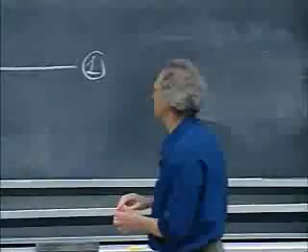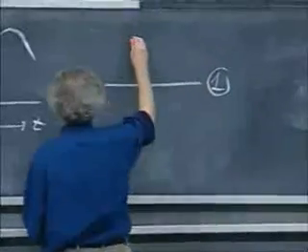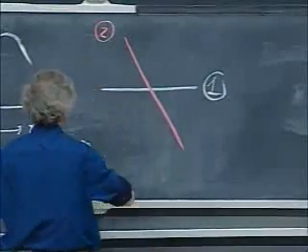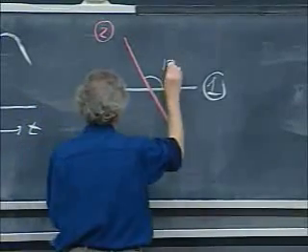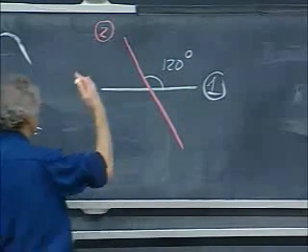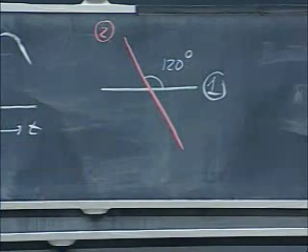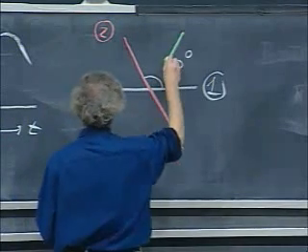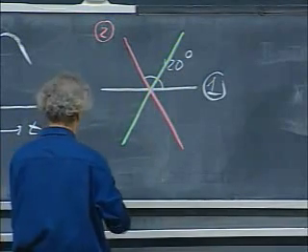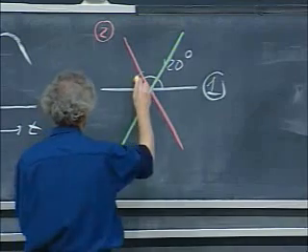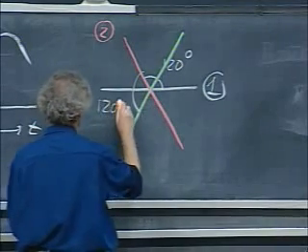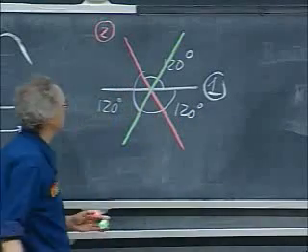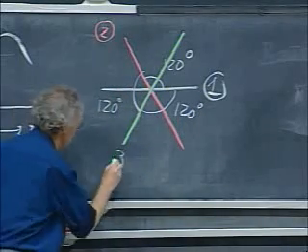And so in this picture, you will see it like so. Loop number 2, and this is 120 degrees physically rotated. And then I have a third one, which is again 120 degrees rotated, like so. And so this angle here is also 120 degrees, and this is my loop number 3.